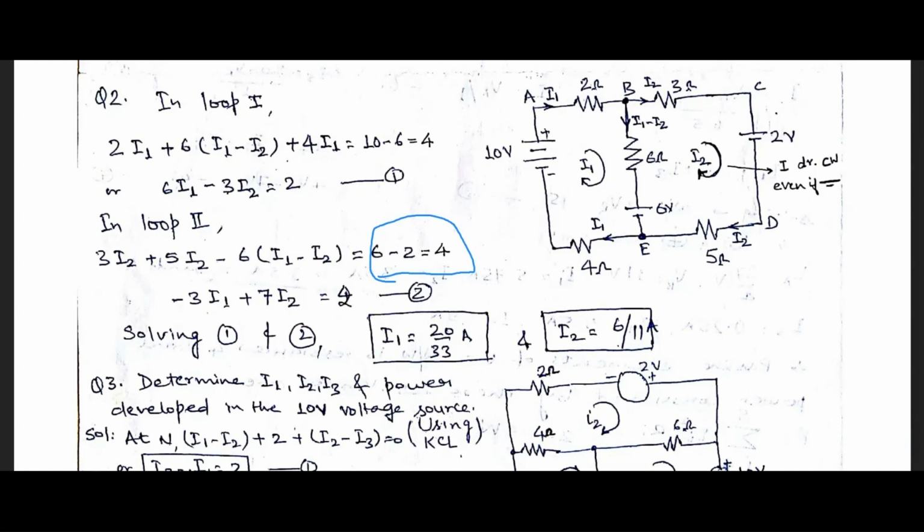So we can also do one thing for clarity in solving the circuits further. If we are focusing on the first loop or second loop, we can also altogether replace or remove the small magnitude battery and replace the bigger battery with the effective value.